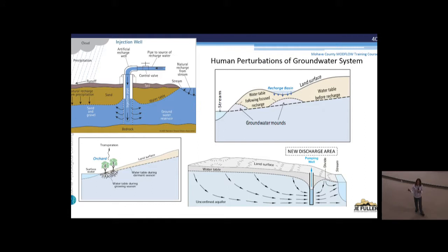So when you start wetting a basin, you see a lot of bubbling. It's hard to get through air. That's part of the permeability of the unsaturated zone, is that it's got air in the way. It has to be overcome, and water has to go around those bubbles. So if you can avoid that, if you can just let it dry on the surface but not too deep, you manage. It's a very important management process, and a lot of people don't understand that. A recharge project is not something you build and walk away from. And if it's an effluent management system, it's actively managed day by day.